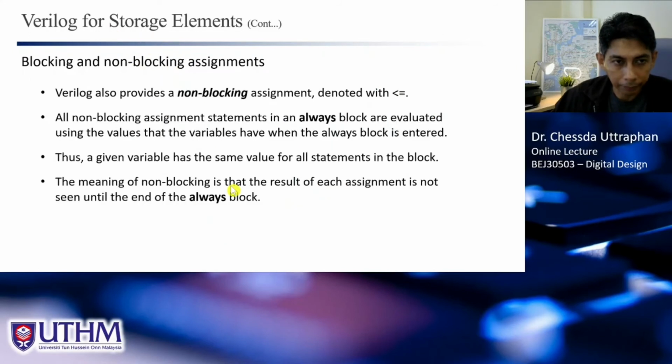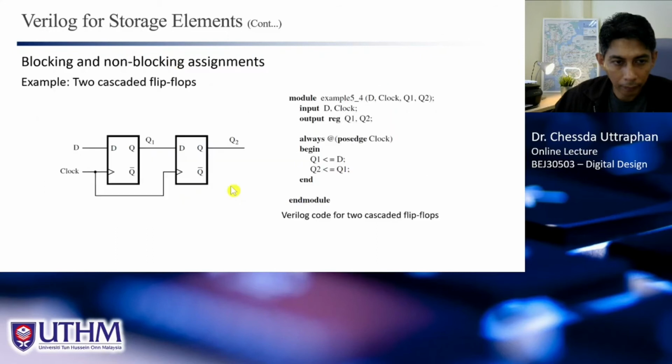Another example. Before that, let's look at the non-blocking assignment. When we use non-blocking assignment, each statement will be evaluated individually. If you write this using non-blocking assignment, it is the same as having two always blocks, where you have this one and this one.